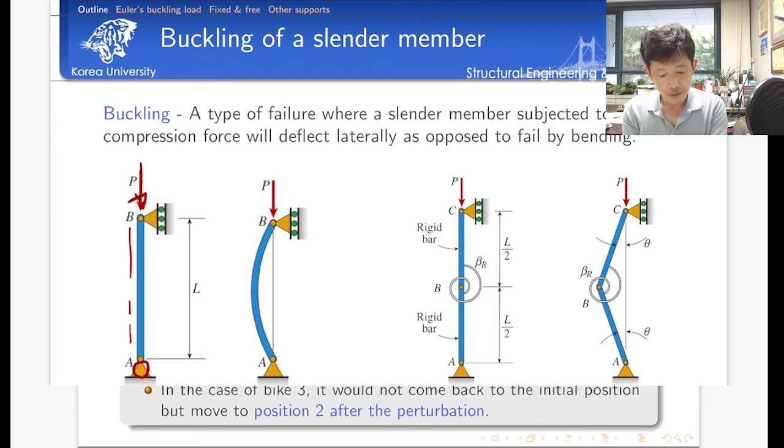If you want to understand this problem in the sense of an axially loaded member, the stress is equal to P divided by the cross-section area. Because this is a compressive force, the stress should be negative. This is a completely one-dimensional problem. But we already understand the nature of the problem very well. If you apply load up to a certain level, then we have a non-zero finite lateral deformation. We already know that.